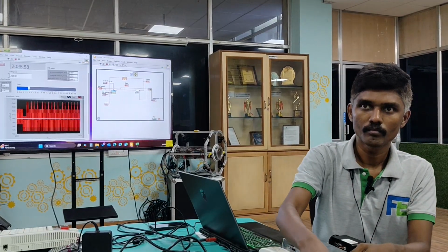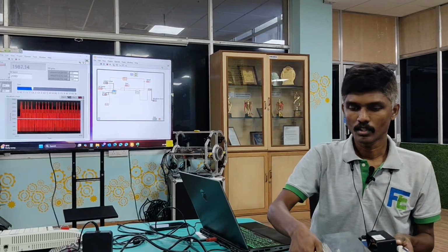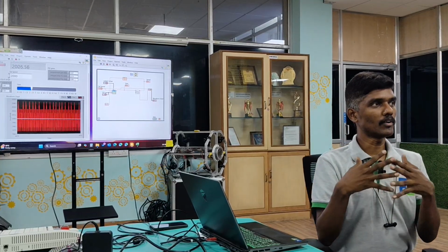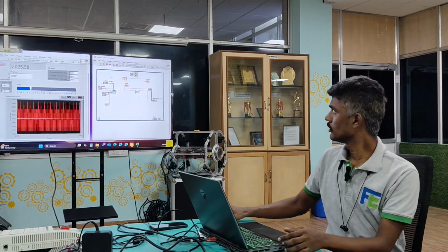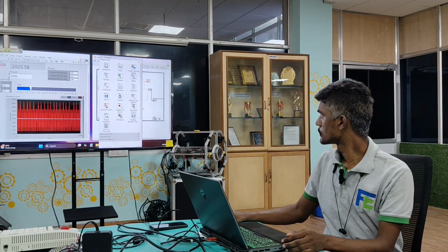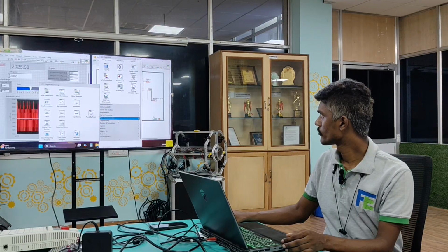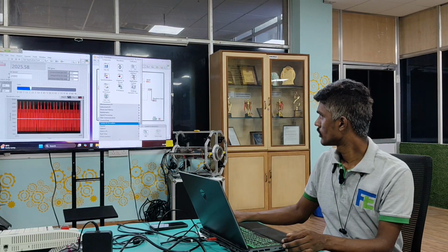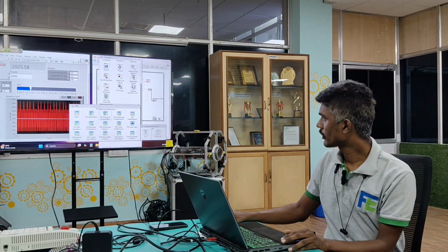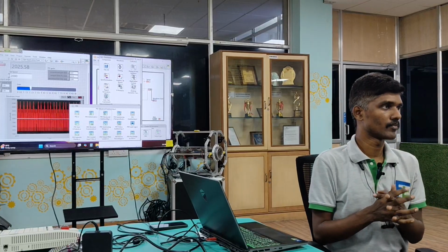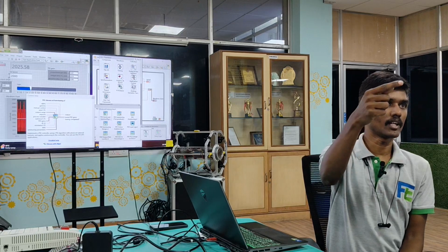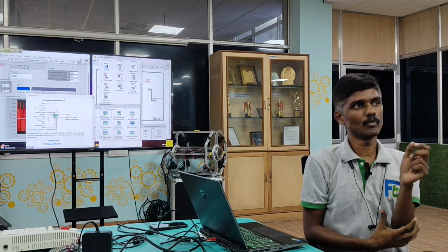So, like MATLAB doesn't have auto-tuning. Auto tune is there, sir. For example, if you want to tune it automatically, I don't want to spend time on manual tuning, then under the PID, I took the first PID block, take the third PID block. So this function having auto tuning PID, what it will have is the PID gain values and auto tuning parameter and one boolean button.